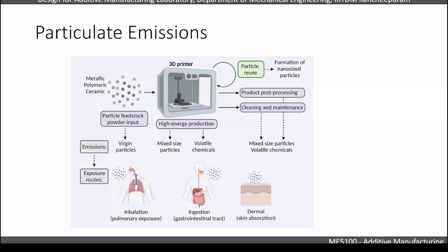Titanium powders and the like readily form a cloud, so safety precautions are needed, and they can also form an explosive charge. When you work with metal additive manufacturing, you need to be really careful. We use a lot of vacuum cleaners with vegetable oils to filter out those particulate emissions, and we need to treat them before we let the fumes outside. There are a lot of metallic, polymer and ceramic particles, right?